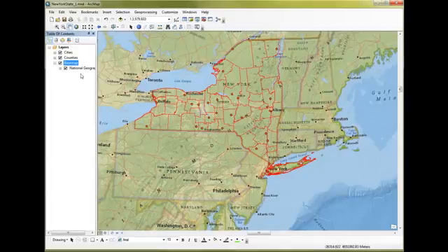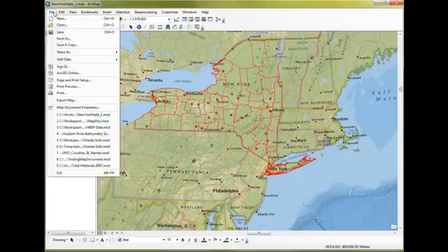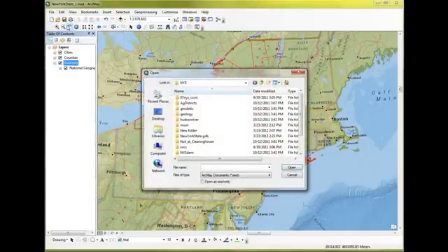Now, let's just look at the menus. I just wanted to hit upon three menus today. The File menu, very easy one to follow. If we left click on the menu, we get our choices for New and Open. These are opening up either a brand new map document or an existing map document. And of course, if you press Open, you're going to get a browser window and want to go navigate for a map document. And notice at the bottom here, it says MXD for the type.